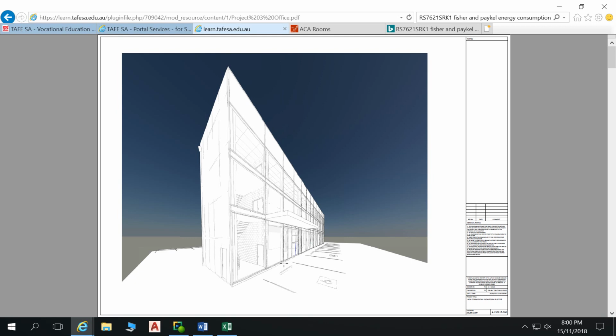They say if we're using this particular stud system, we have to provide this insulation and this layering of fire check plasterboard to give us that FRL. So you can take pretty much any wall and produce a fire separation wall out of that by utilising some of those components. So timber stud walls, most definitely you can use as fire separation walls if they're treated correctly.